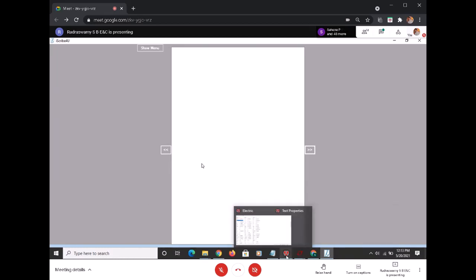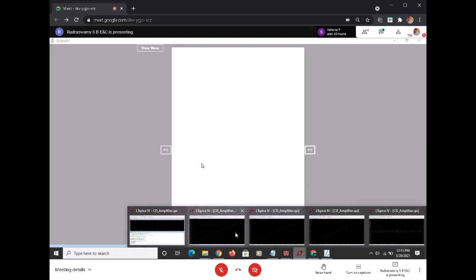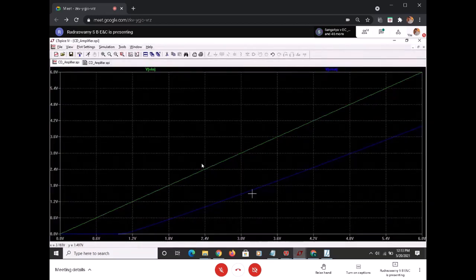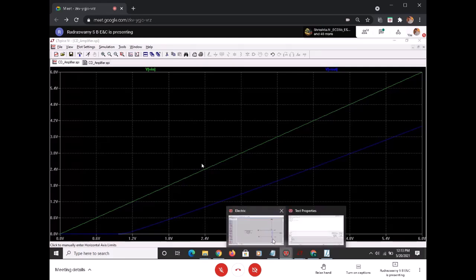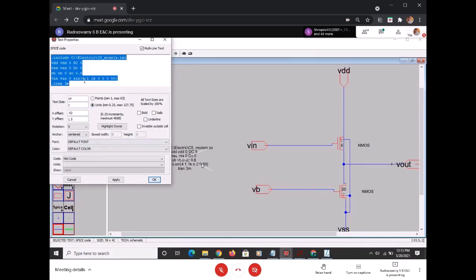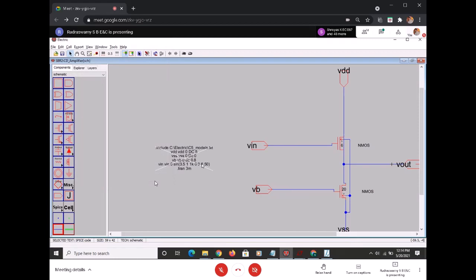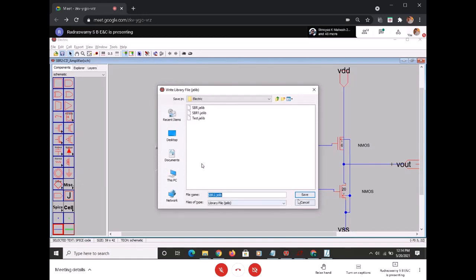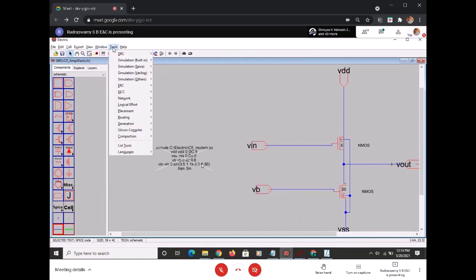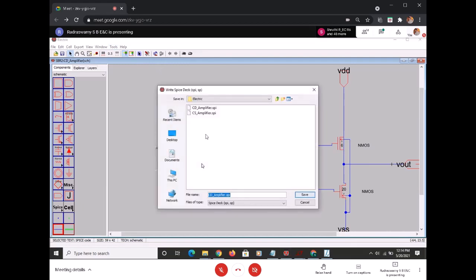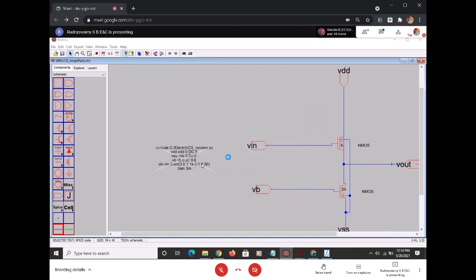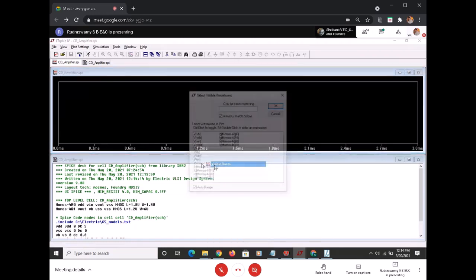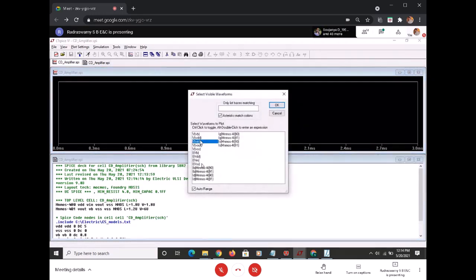Similarly, we can go ahead. See, all these analyses are important now. So how to choose a DC operating point? Suppose I try to change this DC operating point from 4 to somewhere around 3.5, and we'll see whether something helps or not. Okay, save. Tools, Spice, right click. I'll try to see what really happens with the gain there. Visible trace, V in, V out.